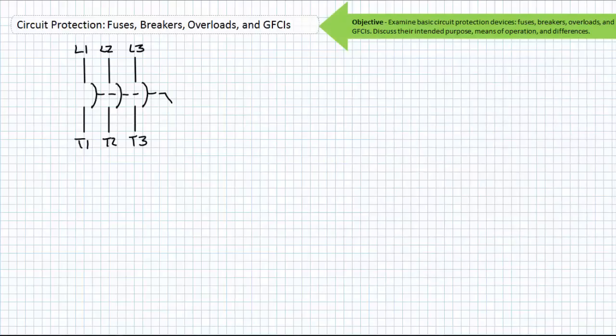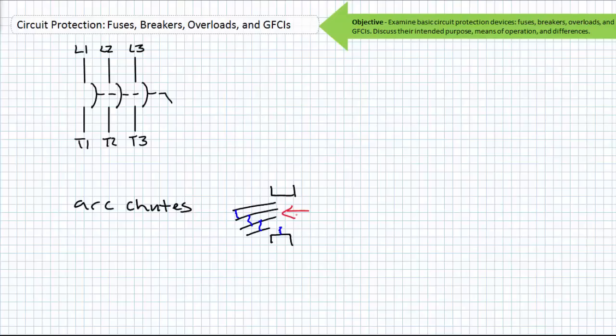This is one of the arc extinguishing means I referred to earlier. There's basically a spring on the moving contacts, and when actuated it rips the contacts apart, like a referee at a fight, and sends them to their respective corners. This rapid and forceful separation means that the arc that could potentially form between these contacts is given less of a chance to do so. Additional precautions are often used to minimize this arc. Larger circuit breakers use arc chutes to divide and cool the arc. Blowout coils or other magnetic means deflect the arc into the arc chute.